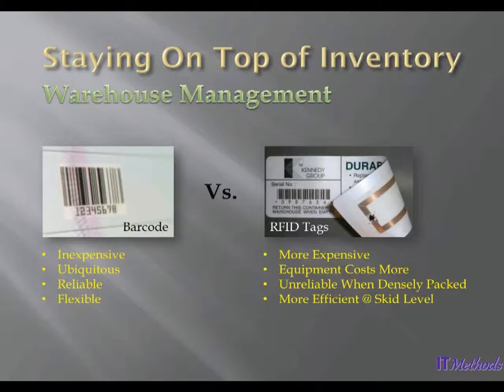Well, if the antenna on the tag is blocked by either liquid or metal, and when I say liquid, it could be a high moisture content in a cardboard box, that could be enough to block a signal. And of course, the tags could be on a product that's in a box, that's in another box, that's on a skid, that's wrapped in plastic, and so there's a lot of barriers between that tag and the reader.